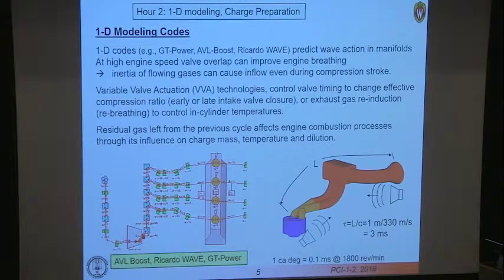So how's that possible? Well, here's a picture that shows an internal combustion engine. Here's your piston, here's your intake valves, and you have a certain manifolding, a certain length of manifolding. Imagine that the piston moves a little bit. So the density immediately above the piston decreases, and that's going to demand fresh gas from the intake system to fill that void. Well, how does the flow system get set up? A signal is sent from the piston at the speed of sound all the way back to the intake system saying, I just moved my piston, please send me some more gas.